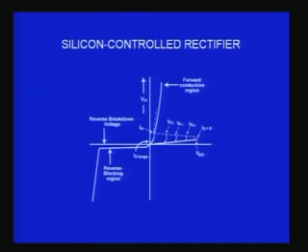And what you have on the left side is the reverse bias. You find it is like a normal Zener diode, except that this reverse breakover voltage will come too far away compared to the forward breakover, because there are 2 junctions now which are reverse biased. After that it becomes something like an avalanche effect, and so you have a reverse blocking region in this region and a reverse breakdown region beyond that point. So this will be the characteristics of a silicon controlled rectifier.